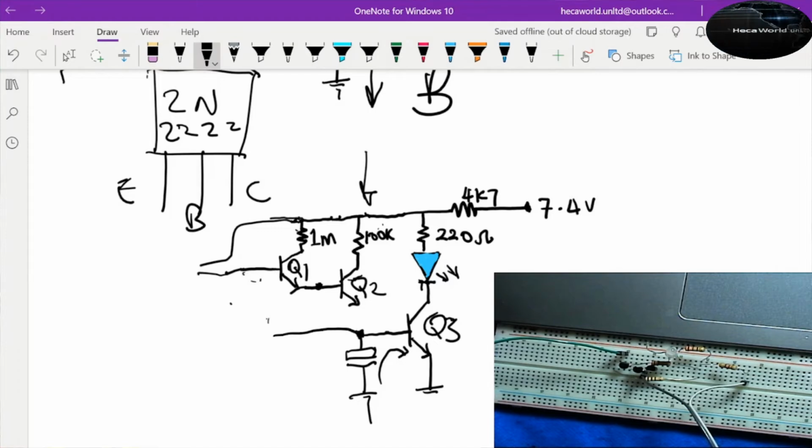So imagine there's voltage coming in here from a different source, V or I current, and it charges this capacitor and is stored here. This capacitor stores this charge in the form of voltage and discharges it through the base of this transistor. Then this LED will come on. That's what we're going to do right now. So let's simulate that. So we're going to connect this way.